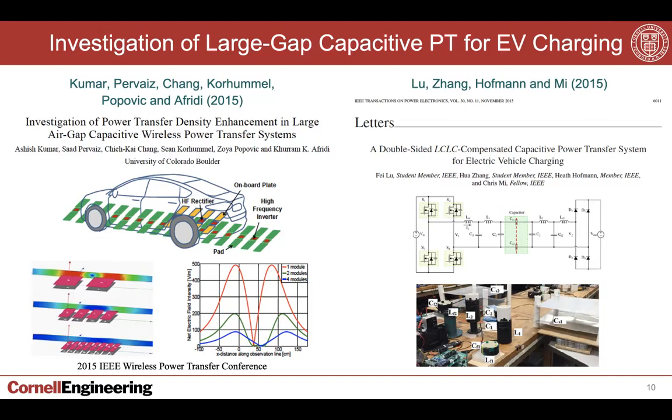And one of the challenges there, as we will understand as I start to talk about the basic principles, is that you have to get to high enough frequencies to make the capacitive impedance look relatively smaller. And in this case, we investigated 6.78 megahertz power transfer.